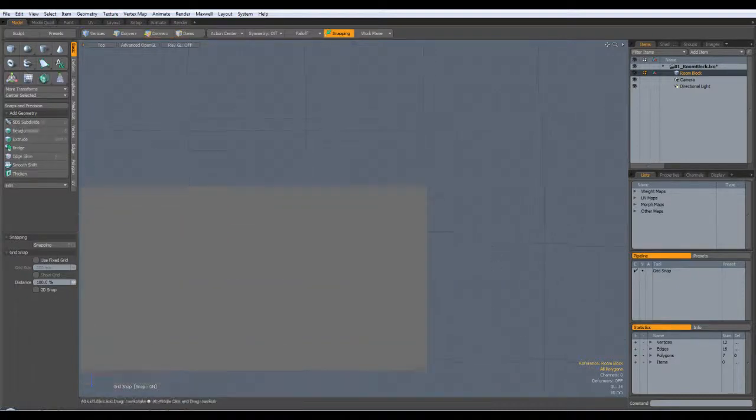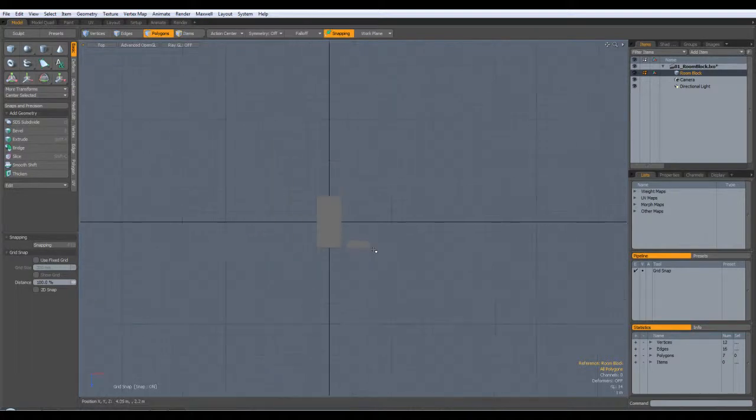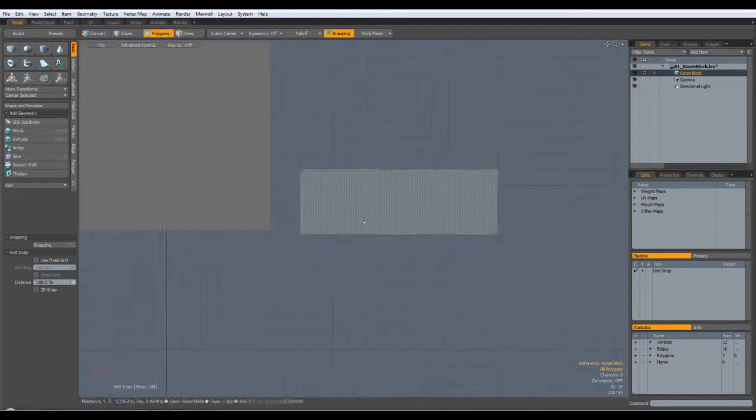But as you zoom in, you see they change. So now we're zoomed in. This is still 800, but each of these blocks now are 50 mil. So that's just something to note when you're placing geometry. You can get quite a good indication of size just looking at the scale there. Now, so we know it's about 4 blocks.